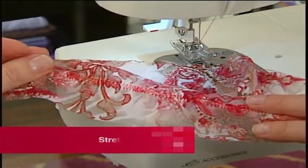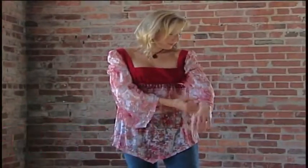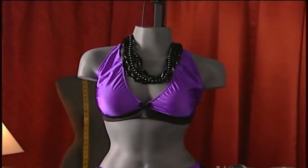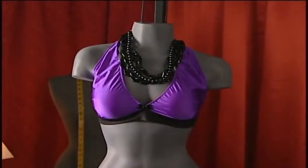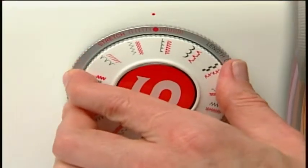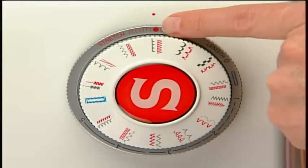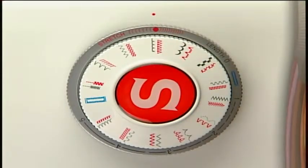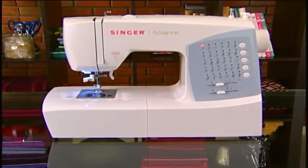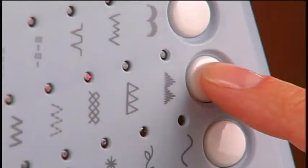Most machines have a selection of stretch stitches. These stitches are mainly used to sew fabrics with an elastic quality, like those used to make activewear and swimwear. Most mechanical machines with stretch stitches require you to set a lever or dial to the stretch stitch mode in order to select the stretch pattern. Electronic or computerized machines automatically set the stitch for stretch sewing when the stretch stitch is selected.